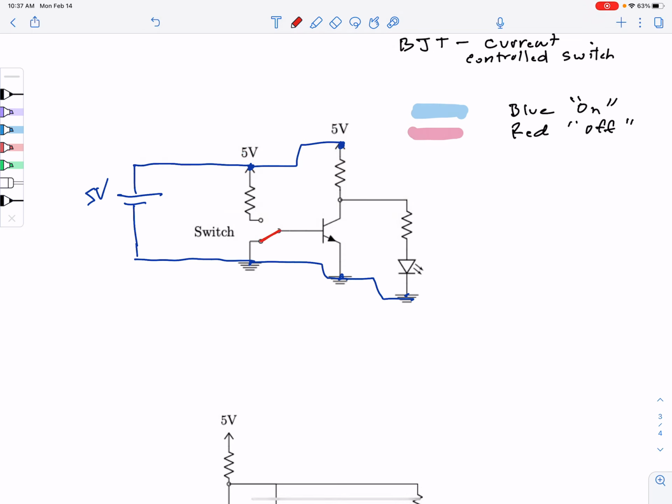We'll start with down. All right, and the very first starting point that you want to have is to try to figure out whether the transistors are on or off. Okay, and so a quick way to check on this is that this is at ground, so it's at 0 volts, and so is this. The other side of this transistor is at 0 volts.